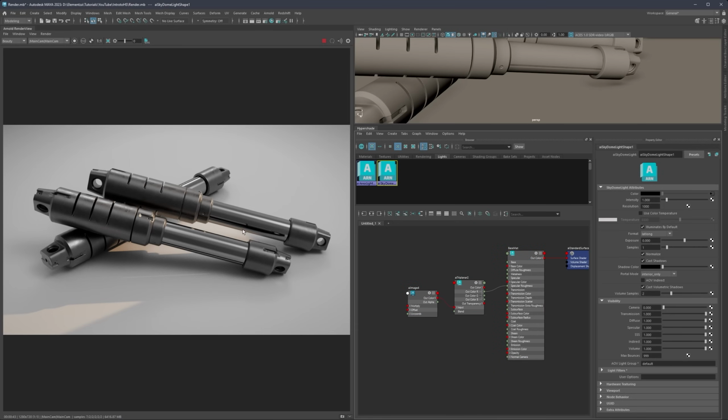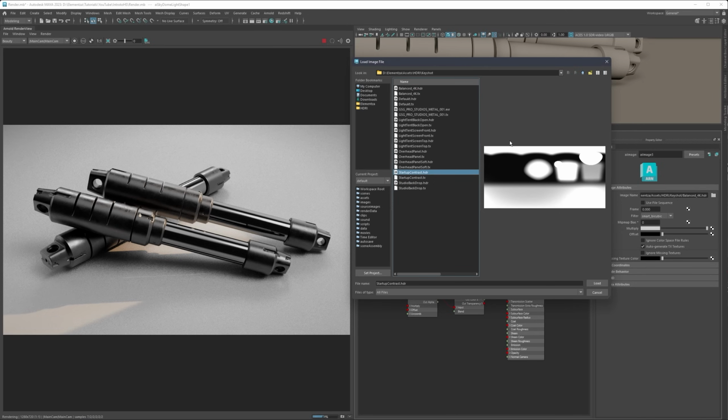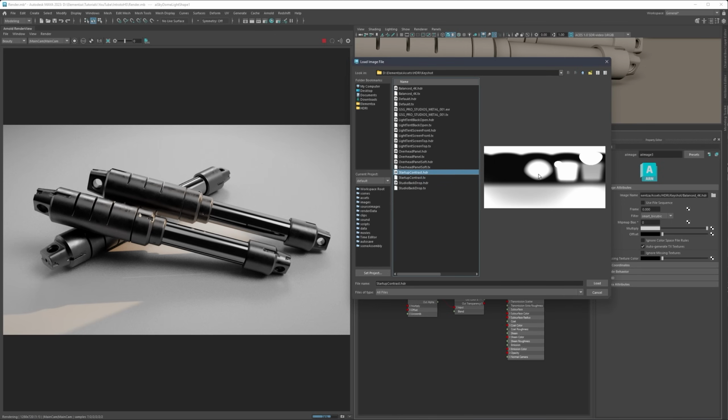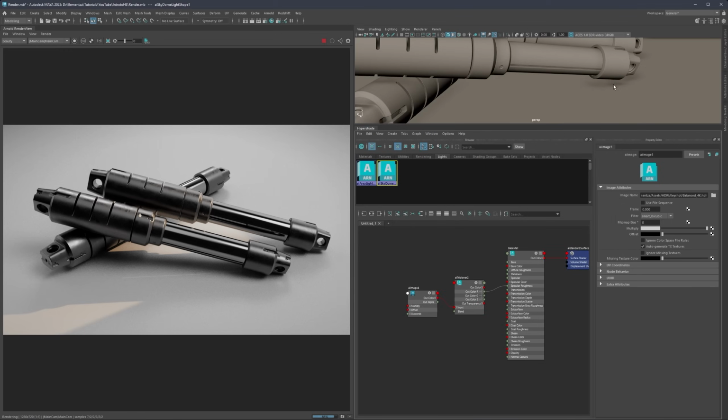So now we can also do one final thing, and that is go into lights, sky dome, and now we can actually try and load in an HDRI that has slightly more contrast. For example, this is the map that I loaded in. As you can see, it's slightly more contrast than what we have here as a balanced one. This one is going to be very, very subtle. This one is going to have more darker tones.